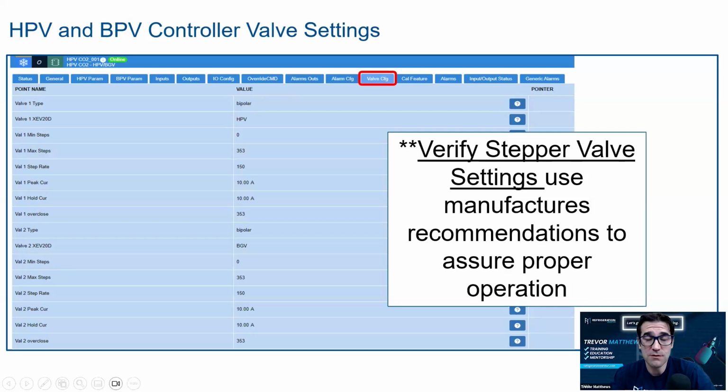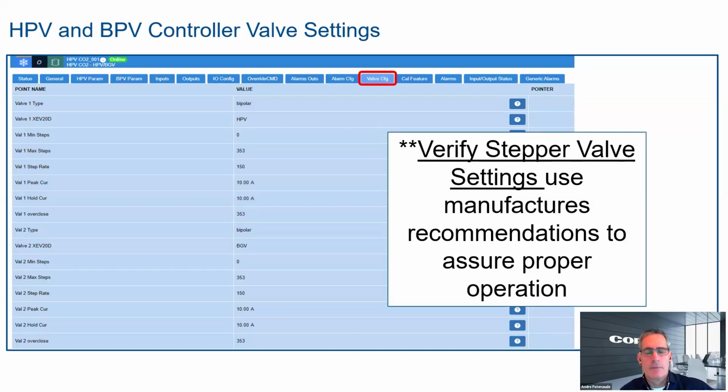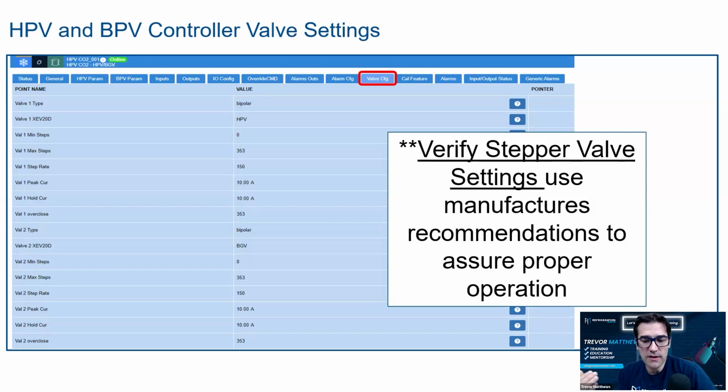Super important. That's a really good point. I had someone call me about a month or two ago and said they have anti-relief that keeps leaking. It keeps bleeding out. And I think there was a CDS valve that they had on the anti-relief. So this is before the pressure relief goes, it'd be like a burp valve. I remember Andre at the ILC, there was a burp valve on that cascade system. Yeah, absolutely. We call it burp valve anti-relief, but they're asking me like, we don't know why it continues to leak and it won't 100% shut.